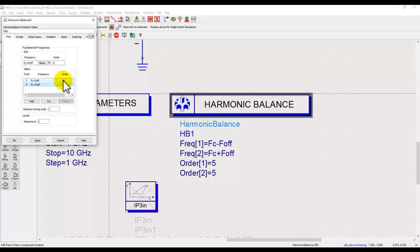That means for the intermodulation products, the maximum order which can get generated is 10, which is 5 plus 5. So as you understand from theory, the intermodulation products will be denoted by the formula M F1 plus or minus N F2, where F1 and F2 are the two tones we are feeding to our circuit, and M and N are indices, which is nothing but these order indices.